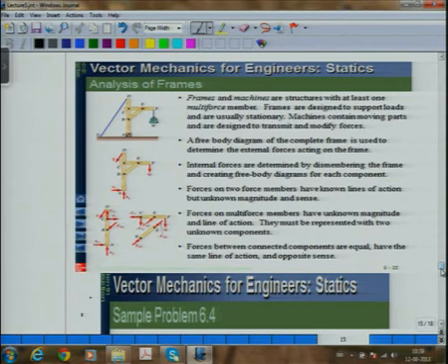Now the next key step in these problems is, if I draw the free body diagram of CEF, and I have shown these as Cx and Cy, then the forces at C will be opposite. It will be minus Cx and minus Cy, and I have already found these out. I have already found out BE, so all I have is F here, and actually I have already solved all the forces. So it should verify when I do my equations.